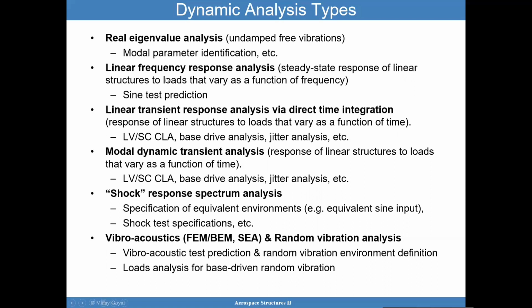You also have the linear frequency response analyses, where there's a steady state response associated with loads that vary as a function of frequency. We also have the linear transient response analysis via direct time integration. So you're looking at the response of linear structures to loads that vary as a function of time.